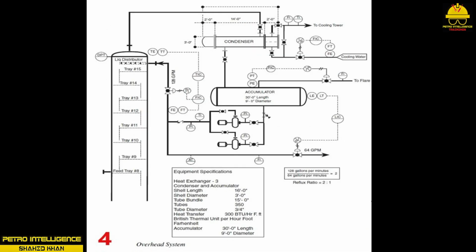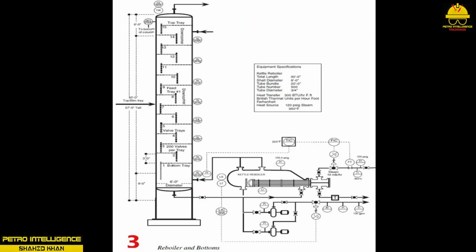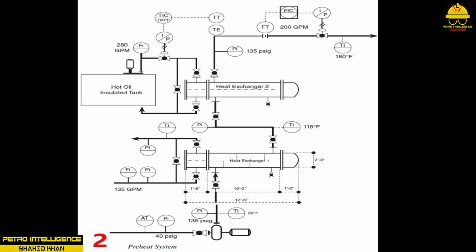7. Set the overhead, bottoms, and off-spec tanks to 50% and place in auto. Line up off-spec tank, column bottoms and top. 8. Line up unit feed pump and both exchangers. Shell side first, then tube side. 9. Set unit feed FIC to required set point. Most units will increase feed in 50 GPM increments.